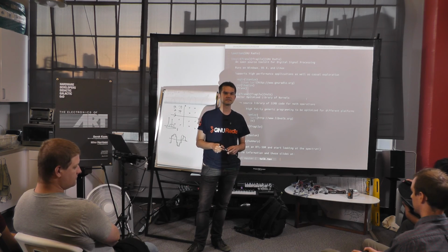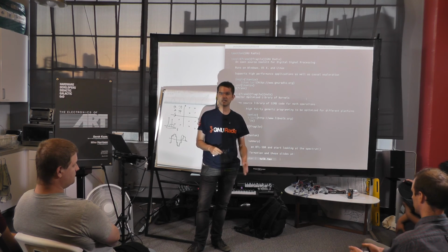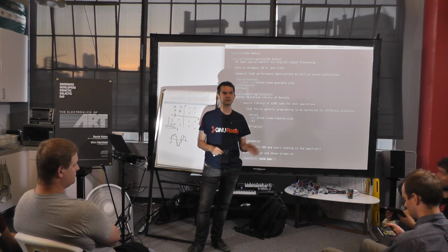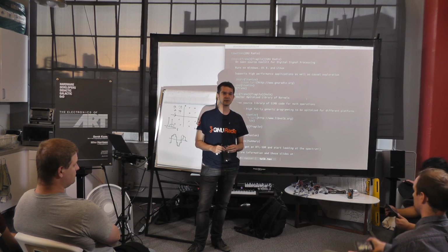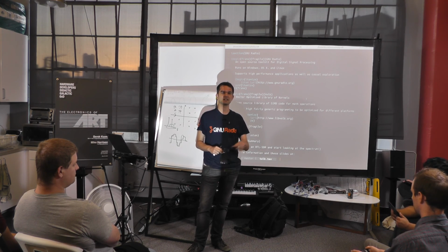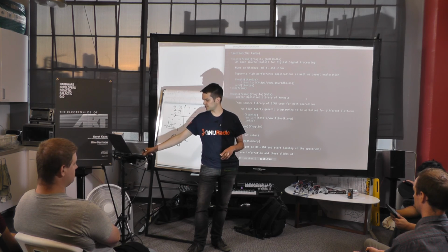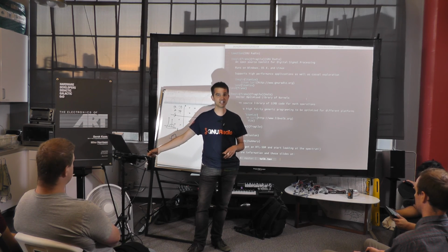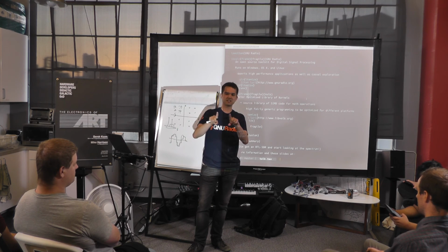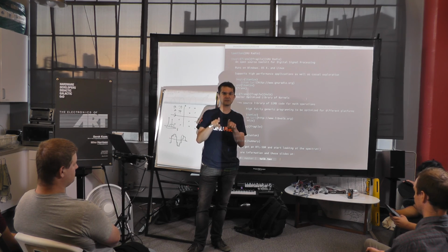Yes? Are you allowed to transmit at 200 watts? Yes, you are. At the low end of 10 gigahertz, you have to be careful in the US because the government runs radar at that same frequency, and there's a lot of stuff coming, like road radar. But if you have a satellite dish pointed at the moon, one of the choices you get with antennas is how much gain you get, and that basically always comes at the cost of directionality.